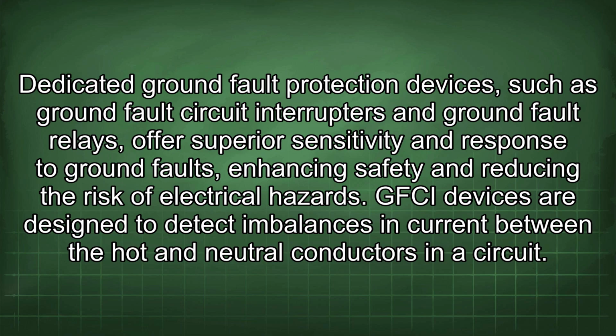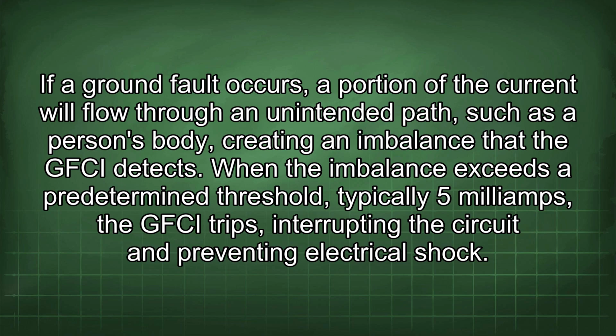GFCI devices are designed to detect imbalances in current between the hot and neutral conductors in a circuit. If a ground fault occurs, a portion of the current will flow through an unintended path, such as a person's body, creating an imbalance that the GFCI detects.